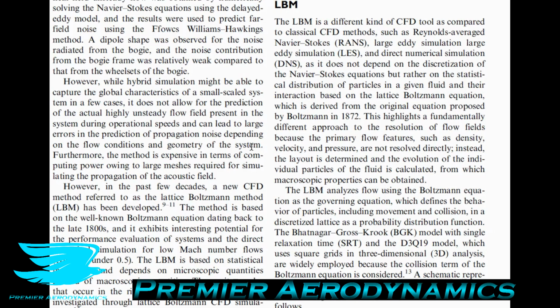Now, for the Lattice Boltzmann method, you do the same thing, but they're called different things. They're called surfels and voxels. And the voxels are effectively the equivalent of a Navier-Stokes CFD cell. I just want to touch upon that there.